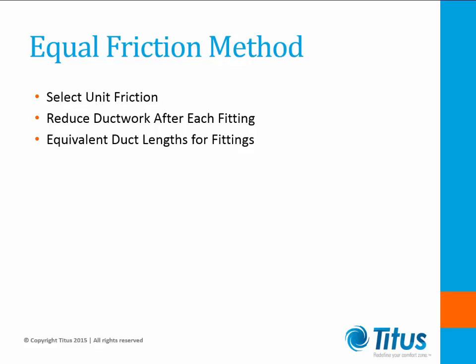With the introduction of computer-aided duct design, the lookup tables for fittings waned in popularity, and have been replaced with computer-calculated fitting losses. A modified equal friction method is still a popular method. Ductwork is sized for unit friction limits, and fittings are calculated using a duct design program.